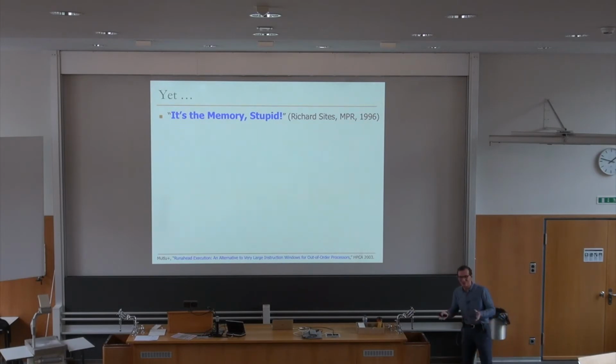Well, in some places you can actually use that, it's a very beautiful architecture actually, but I think it's not used anymore in anything, it didn't even survive. But this was the fastest processor of its time, and basically it was able to finish 4 instructions per cycle. And one of the things that he mentions is that in one of the important workloads for this architecture, they figured out that it's finishing 1 instruction every 4 cycles. I think it was a database workload, for example. Basically, this processor is operating at 1/16 of its peak bandwidth in terms of computation.